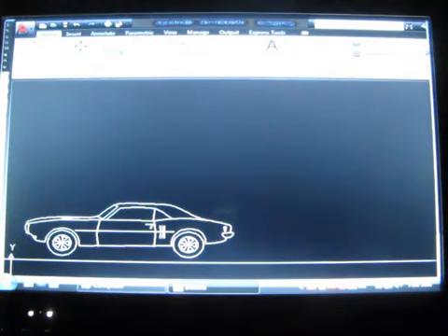If you were to create a drawing with pencil and paper, you would start off by defining your border and title block so you know where to draw. Then you put your objects inside that. AutoCAD works in reverse. You create your drawing objects or your model in model space. Then you switch to paper space and add all of your drawing borders and title blocks and information that belong with a drawing.